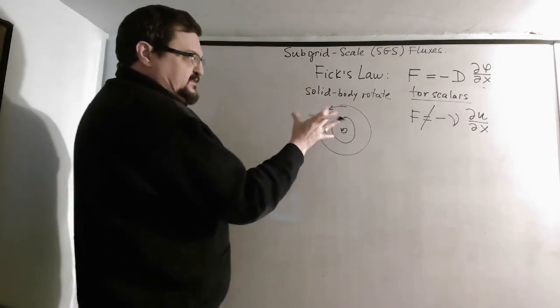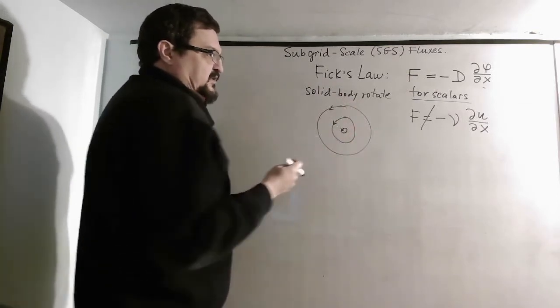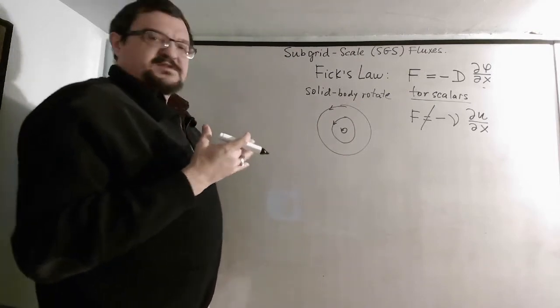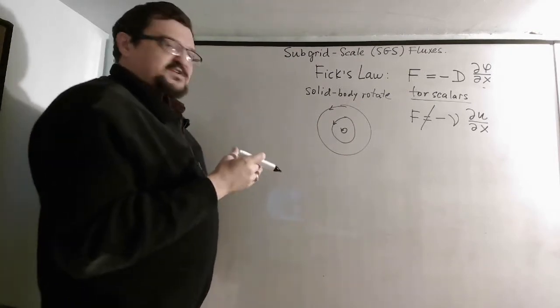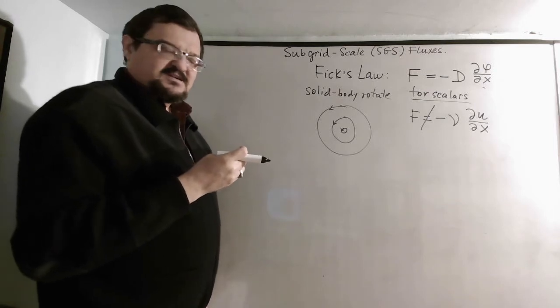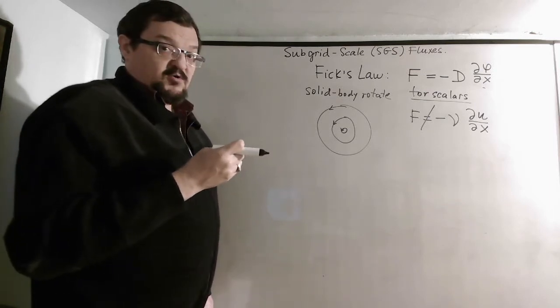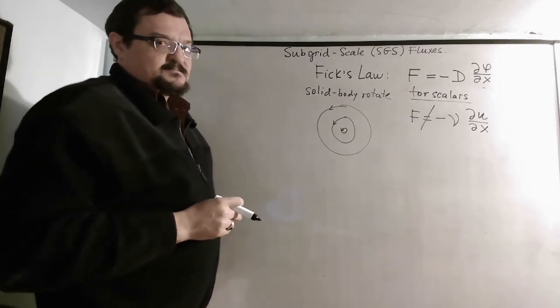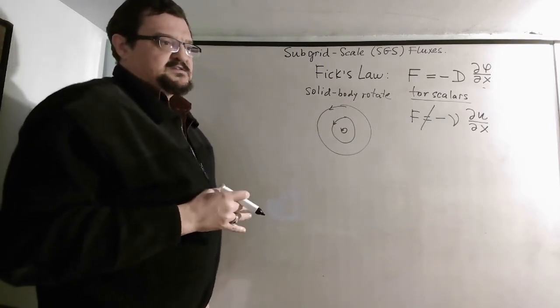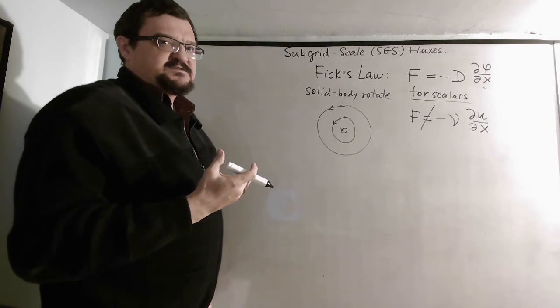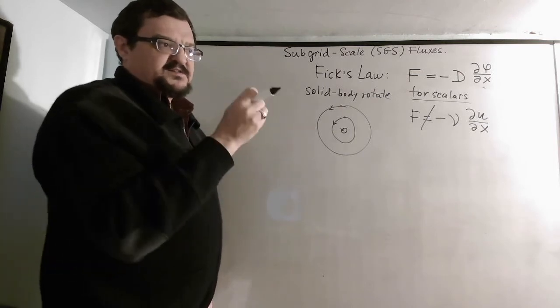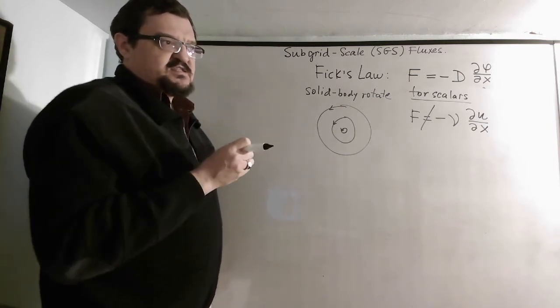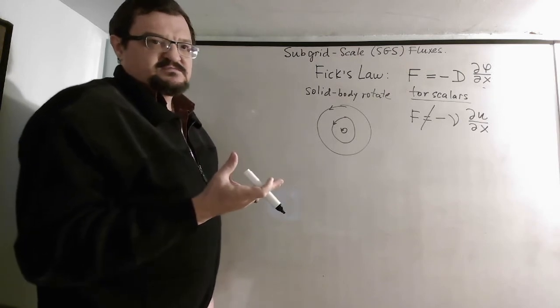It's solid, that's why it's called solid body rotation. Obviously, if it's a solid body, there is no relative movement of velocity or momentum relative to each other, and if there is no relative movement of parcels of fluid relative to each other, there is no diffusion.